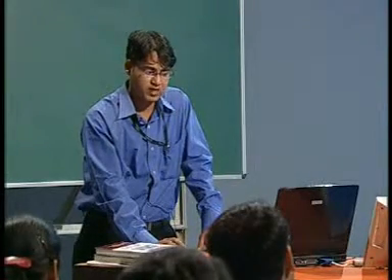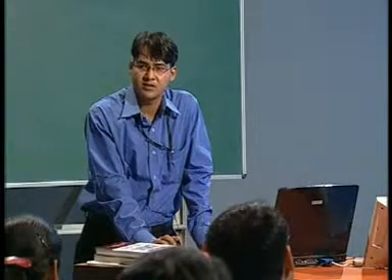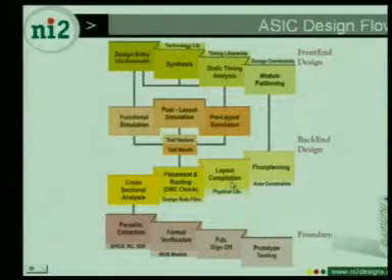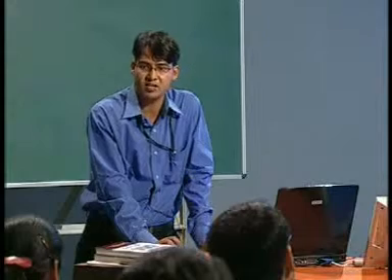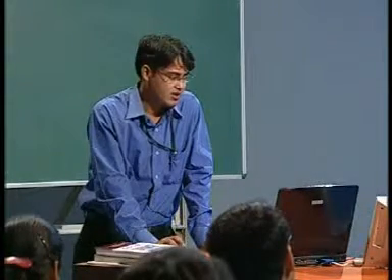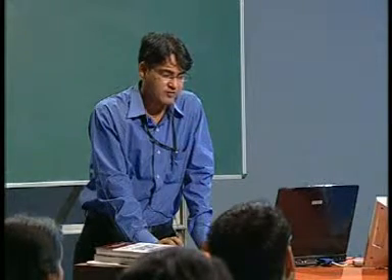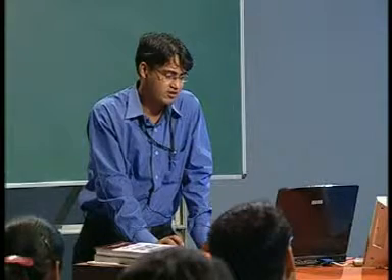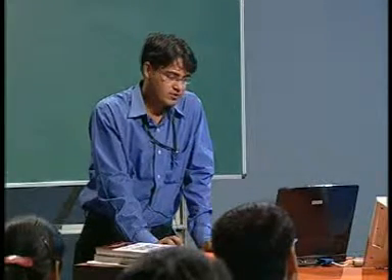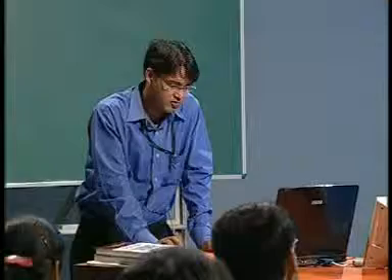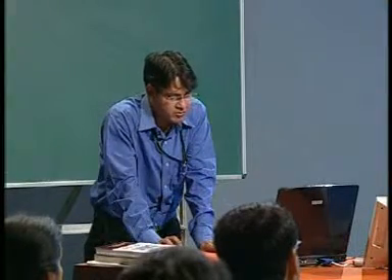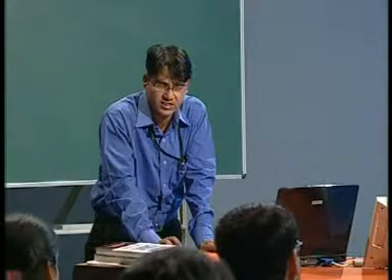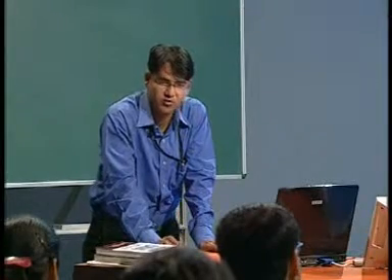After that we will go for layout compilation. Basically, you have to compile your layout, create the mask for your chip, and then do place and routing. I will explain this in depth using the software, because that will be the best way to explain it. And after that we will go for cross sectional analysis. These are analyses like parasitic extraction analysis, and there are a few more.